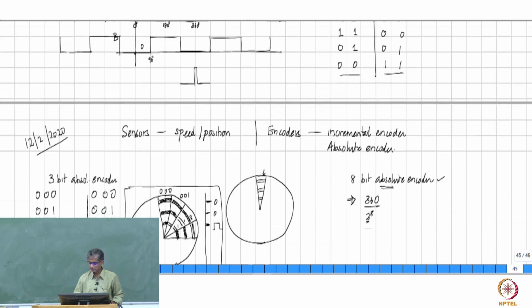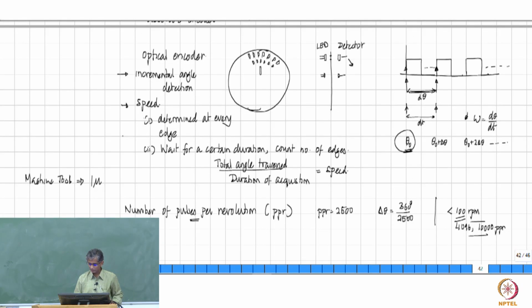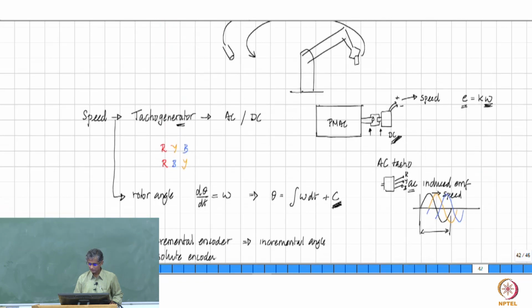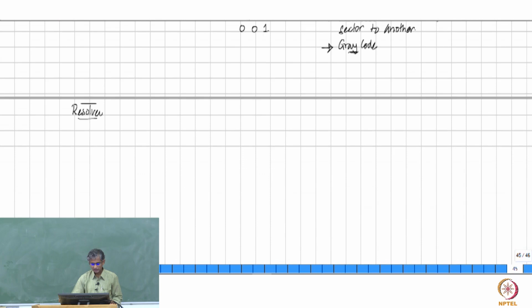But on the other hand, if you are going to use electromagnetic equipment, which is like what we saw here, especially if it's an AC tacho, right? Here you don't have a difficulty because you are only looking at induced EMF and dust is not an issue at all, right? So one can go a little bit more into this and have another entity known as resolver.